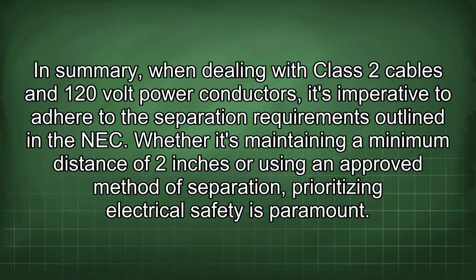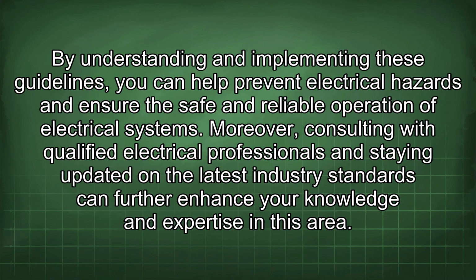In summary, when dealing with Class 2 cables and 120 volt power conductors, it's imperative to adhere to the separation requirements outlined in the NEC. Whether it's maintaining a minimum distance of 2 inches or using an approved method of separation, prioritizing electrical safety is paramount. By understanding and implementing these guidelines, you can help prevent electrical hazards and ensure the safe and reliable operation of electrical systems. Moreover, consulting with qualified electrical professionals and staying updated on the latest industry standards can further enhance your knowledge and expertise in this area.